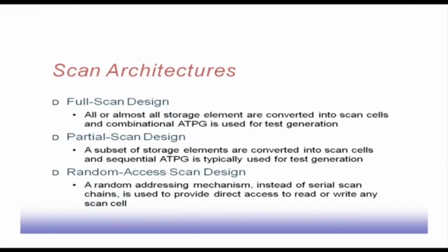Next we will discuss scan architectures. Now, as I have said, in a sequential circuit, for the sake of testing it, we convert it into a scan circuit. There may be a choice in the sense that we may decide that all the flip flops will be converted to scan flip flops, or another option may be that only a subset of the flip flops are converted into scan flip flops, and also in the access pattern by which we can access those individual